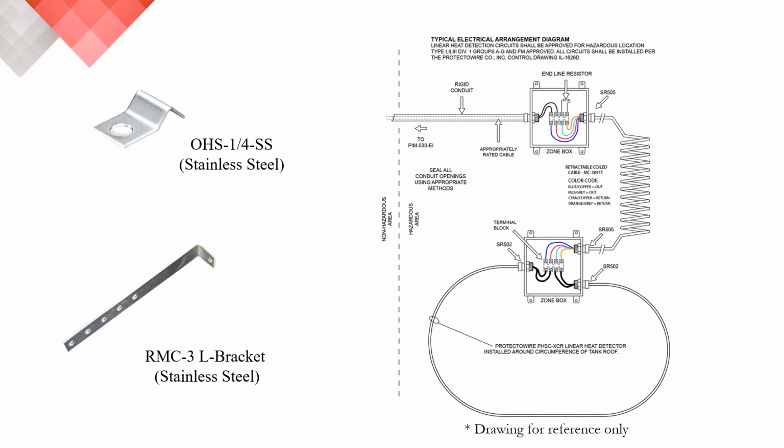Now, once the Protectowire is installed, maintenance and inspection have to be considered. You're not going to just put Protectowire in and forget about it. Maintenance and inspection is required, and if something goes wrong or there's an issue, the mounting brackets and the detector itself will need to be visually inspected to troubleshoot, as well as for inspections. So keep that in mind whenever you're installing Protectowire. You want to make sure that the install is accessible.